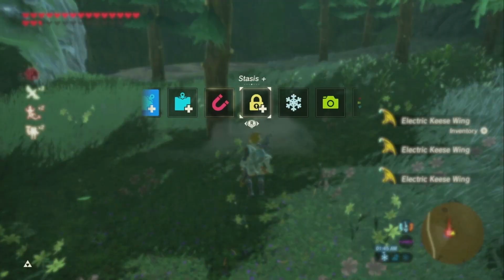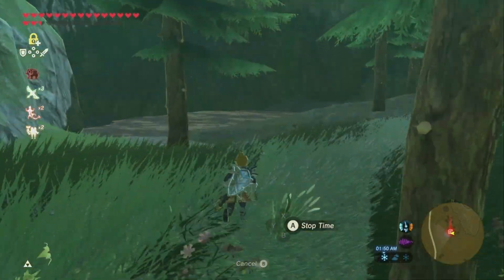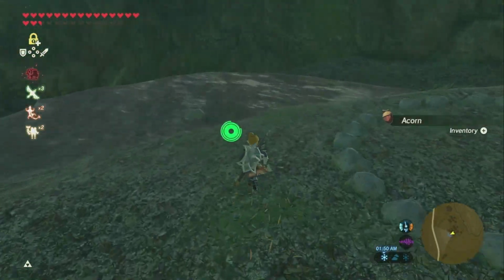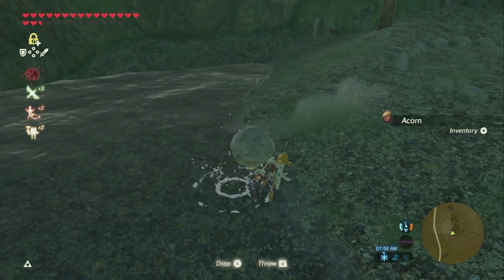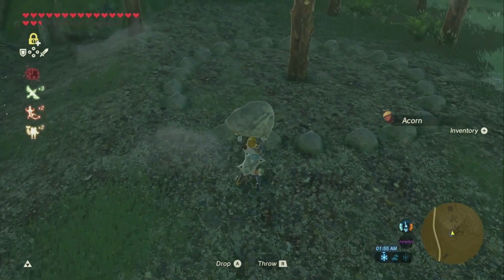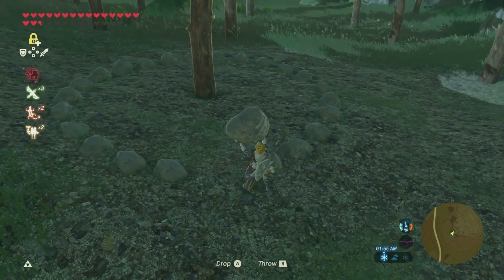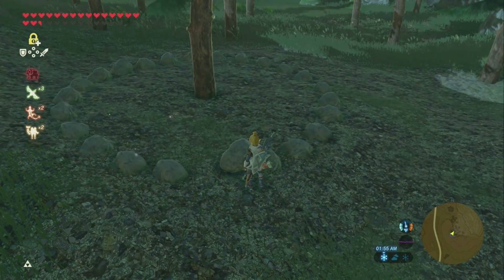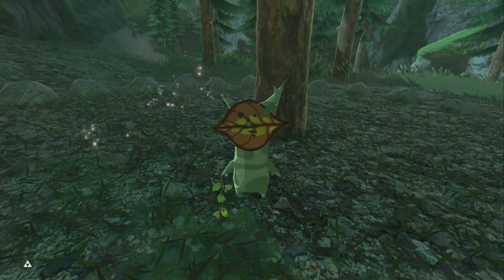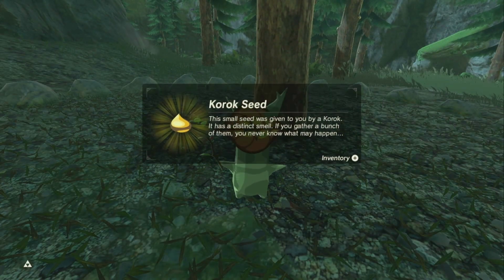Implications. This is a fire hazard and/or a service and replacement problem. If someone has built walls around a water heater, the replacement costs are going to be much higher than average. Strategy. Look on the data plate for the required combustible clearances and make sure they are met.